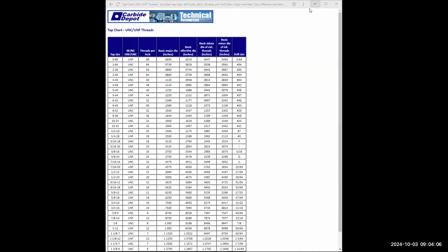Have I lost you? I'll undo it. The first thing I did is type in the word snap ang, which is snap angle. Enter. And it says right now we're at 0 degrees. Well, I want 41 degrees. Enter. And I want to type in line or L, enter. And you can click right here and drag it down to about right there. Click, enter.